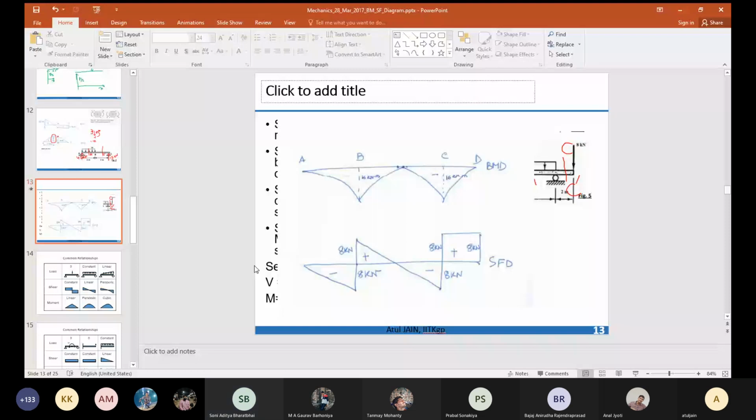Sir, because compared to the bending and the shearing force, the strain will be very small. The twisting and the axial forces are very negligible. That is right, that is absolutely right. What is your name? Ram. Very good, Ram. So if you have a short member, the shear force, if you only apply a point load, is independent of the length. It comes out to be some fixed value.